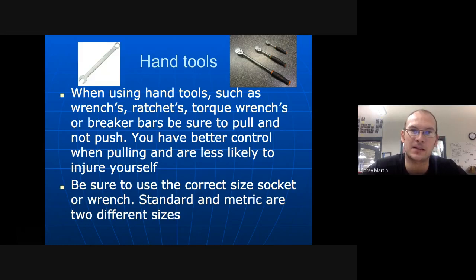So always think about those things while you're doing them. Mistakes can happen, and it can be very, very costly in terms of medical expenses. So always try to make sure you're pulling towards yourself. If you're pulling towards yourself and the tool breaks or the bolt breaks loose, the worst thing that's going to happen is you're going to hit yourself in the chest or leg or arm or wherever.